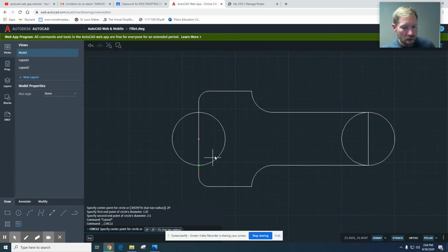So what I'll do is I'll click on circle. And when I built our model the first time, I entered this segment of lines in segments so I know where the endpoints are. If you follow me here, I will hover at the endpoint of that, and you can see it snapping with a green square to the endpoint. The tool that I showed you earlier is polar tracking, and it's really cool because you can polar track here and it picks that up, and I can go north and it keeps it. You can see the little crosshair green stay there. It remembers it. I come over here and find the center point of this circle, which is signified by the quadrant snap. And when I move back towards that first one it remembered, it created my target.